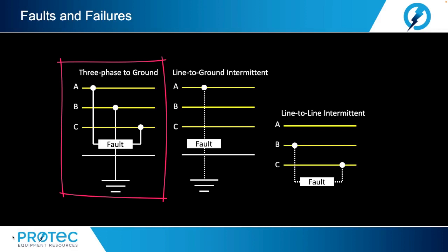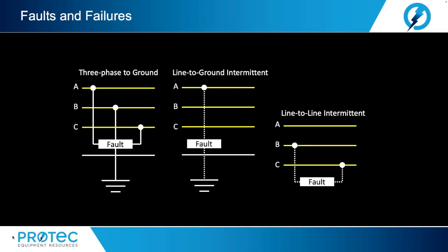Three-phase faults. Faults which involve all the three phases are also known as symmetrical faults. Such types of faults remain balanced even after the fault. These faults make up a very tiny percentage of typical system failures and are often caused by human error. Failure to remove a grounding breaker, leaving ground clusters on systems, and lifting a truck bed or a man lift into an open wire system can cause these types of failures or faults.